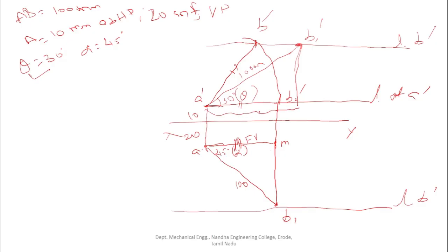You measure this distance, take the center as this one and radius as this distance and make the arc. But it is not a continuous construction procedure. So we are going to measure this distance only, to make the continuity. We erect a vertical line till it intersects the locus of A. Now this point is say B2. AB2 is equal to this distance.